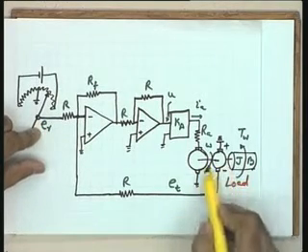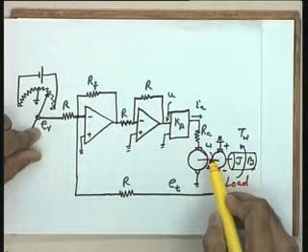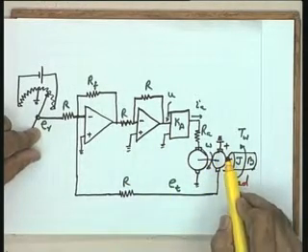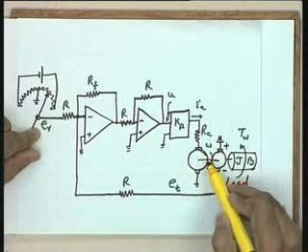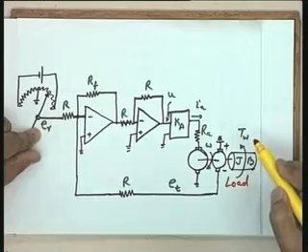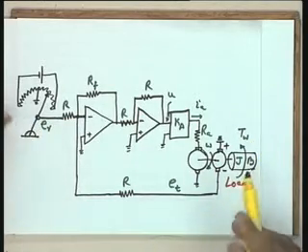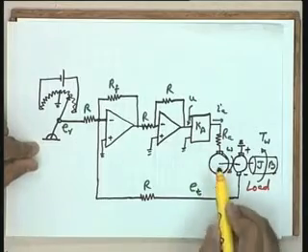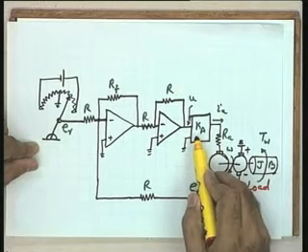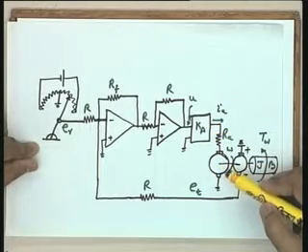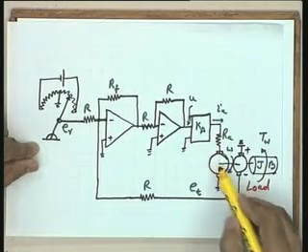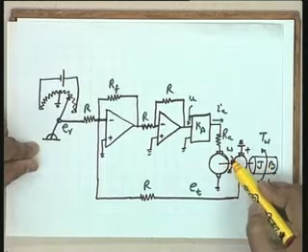Now, omega being the speed, there is a specified omega, and you want the control system to act in such a way that this load runs at the specified value omega in spite of disturbances Tw acting on the system. This is the objective. So, in this case, first of all, I need an actuator, the power device. In this case, the actuator, as you see, is a motor with a power amplifier. This power amplifier and the motor constitute an actuator for this load, because they provide the necessary torque for the load to run at the speed omega.